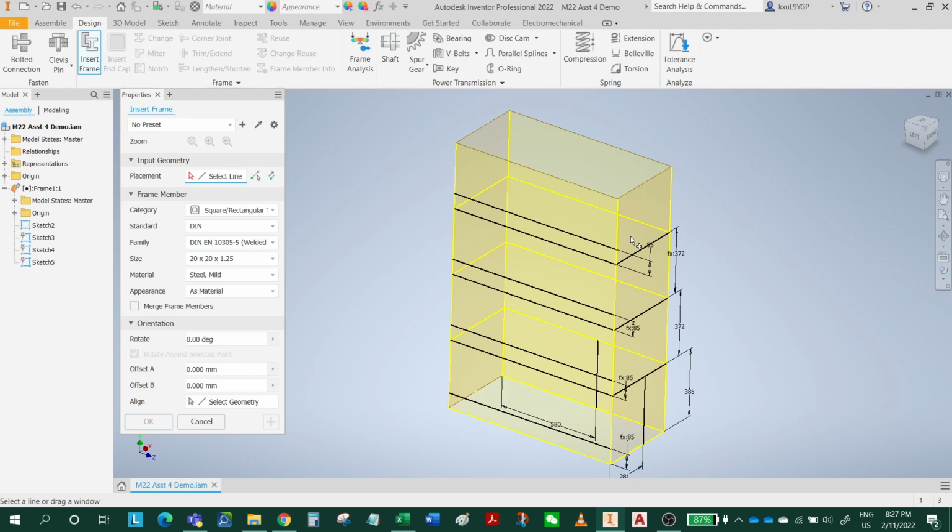From the cut list, we can see that the end treatment for both ends of items 2 and 3 is miter 45 degrees, right? So it means the corner is mitered. That's why we need to select here.